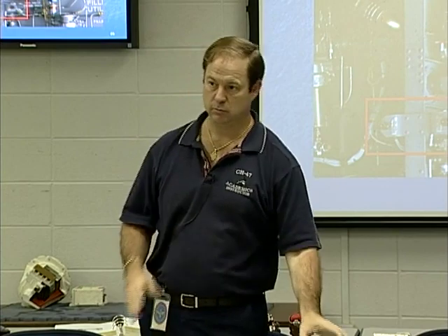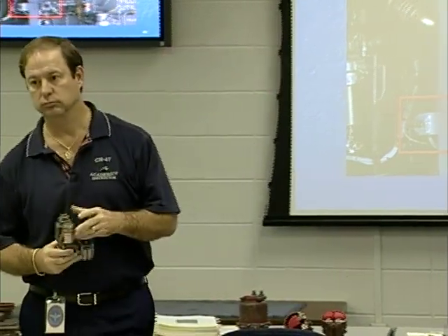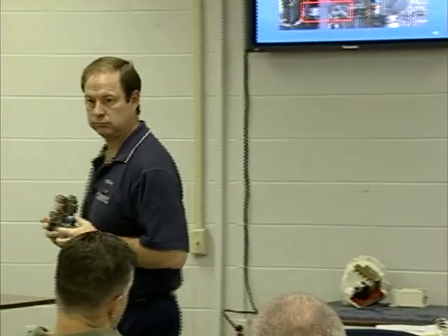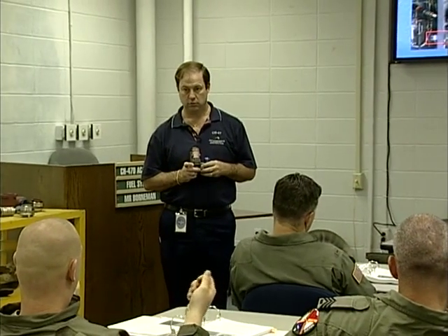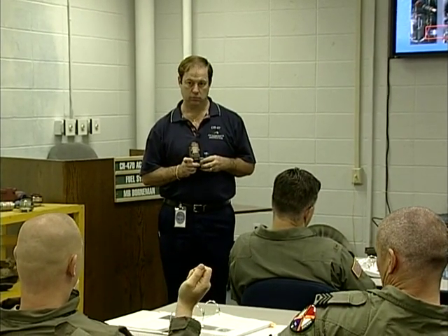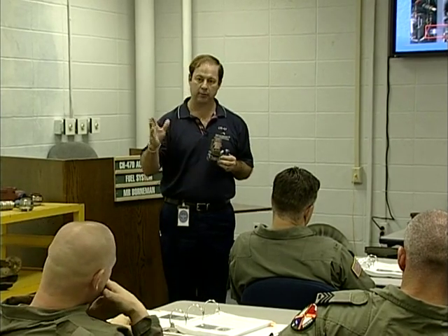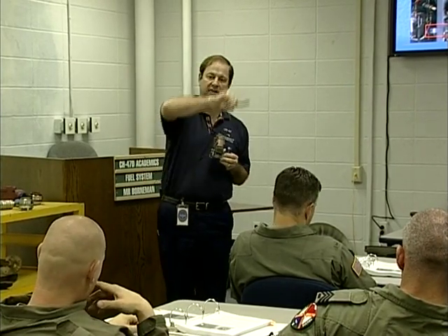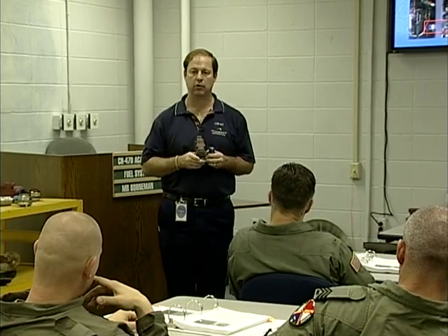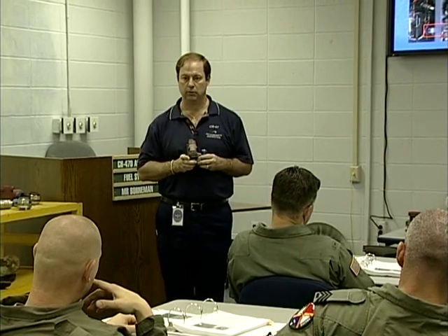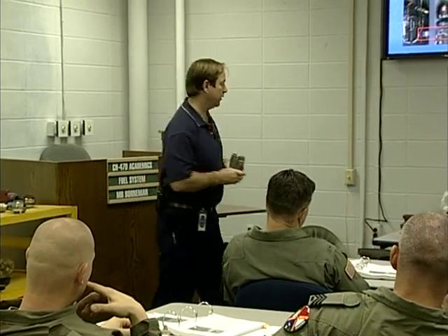So if I open my cross feeds, and for example my right main tank is empty or pump's not working, Yes, sir. I'm going to close the valve. I open the cross feed, but I close the other one. Nope, you're not doing anything. Because there's a lack of pressure on the one side, that's going to dictate which direction through that crossover line that fuel's going to go. Okay? So in other words,